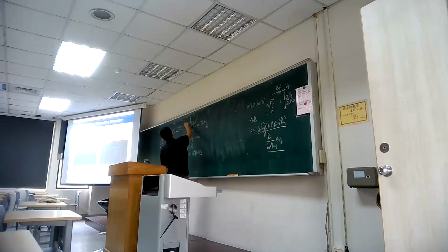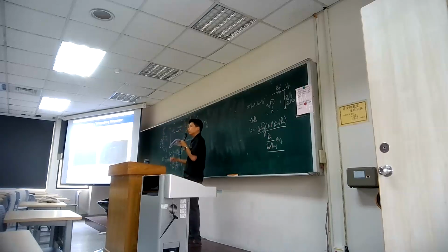So the first thing is that we get a VGS as a charge difference because we get dielectric here. So we have certain accumulation charge, positive charge on the surface of metal, negative charge along the channel. Okay. So it seems there will be a capacitance. So when you charge up and deplete the charge, you get a certain capacitance between. Okay, so that will slow down your response.